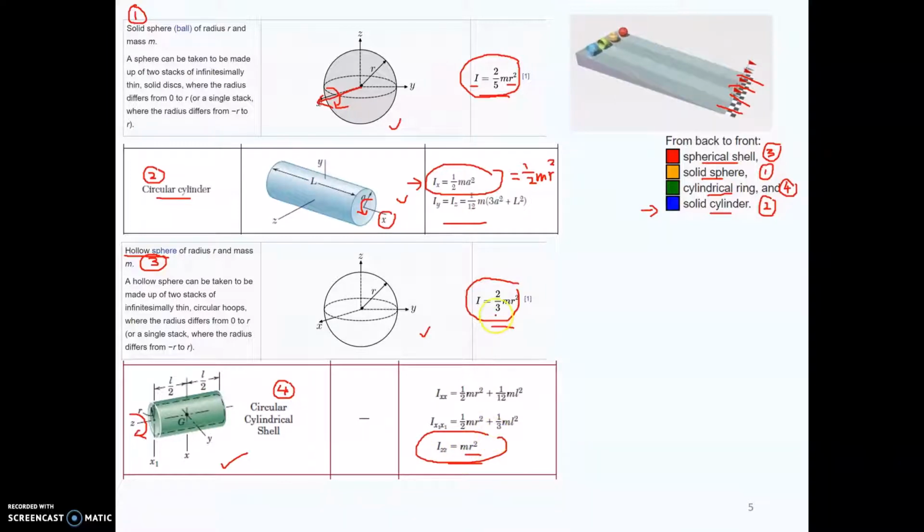When you compare the mass moment of inertia for these four cases, you will see that for case 4 the mass moment of inertia is the highest. And you know that if the mass moment of inertia is high, then the resistance to angular motion will be high as well. This is the reason why the hollow cylinder takes the longest time to reach the ground. The mass moment of inertia for the solid sphere is the lowest. Therefore, the resistance to angular motion is low as well, so it takes the shortest time to reach the ground. So you can see it reaches the ground first.